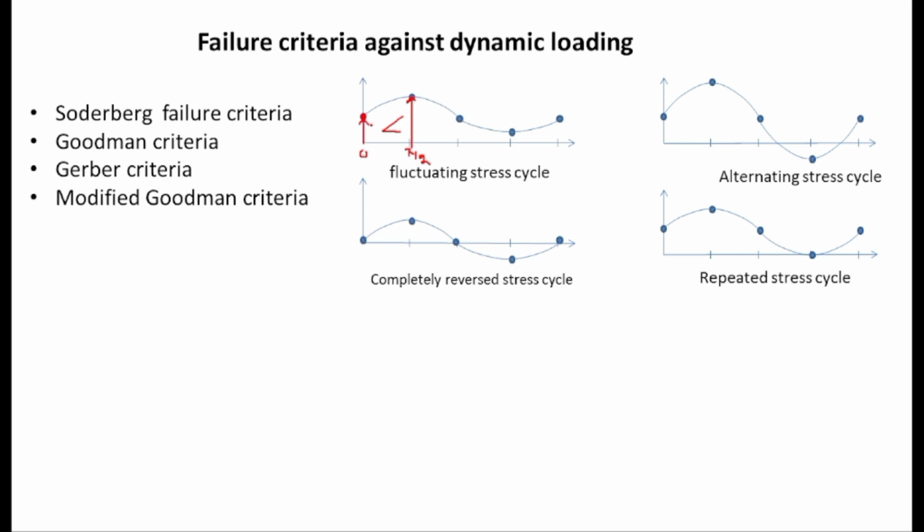Now after that the stress again has decreased because of the decrease in the load at point pi, and for 3 pi by 2 the stress now is equal to this, and at 2 pi or 360 degree the load is this. You can see the cycle that the value of the stress or the value of the load is not constant, it is constantly changing. So you can say that this is the dynamic load.